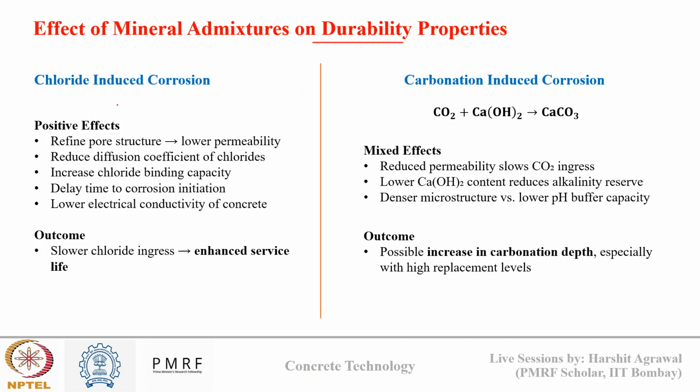How does this happen? When chlorides and carbonates from environment penetrate through concrete and reach the steel reinforcement surface, they can break the passive layer which is present over the steel reinforcement and corrode the steel reinforcement. Once this steel reinforcement is corroded, its effective cross sectional area decreases, and thus the tensile strength of concrete reduces and it causes durability issues to concrete.